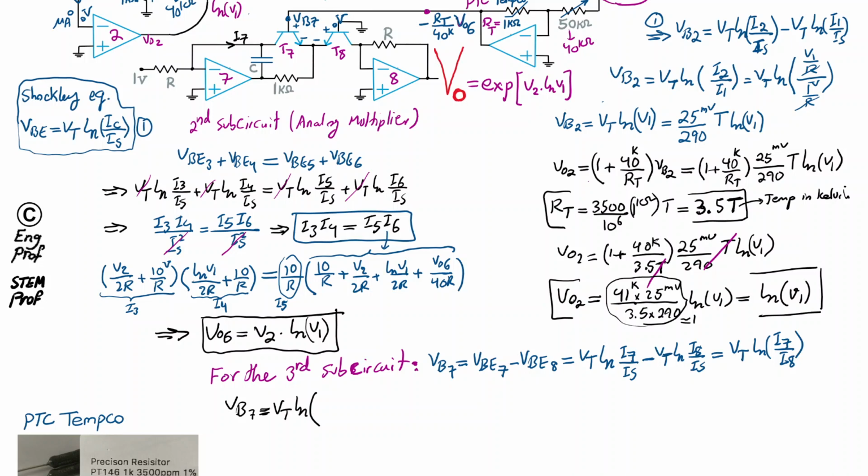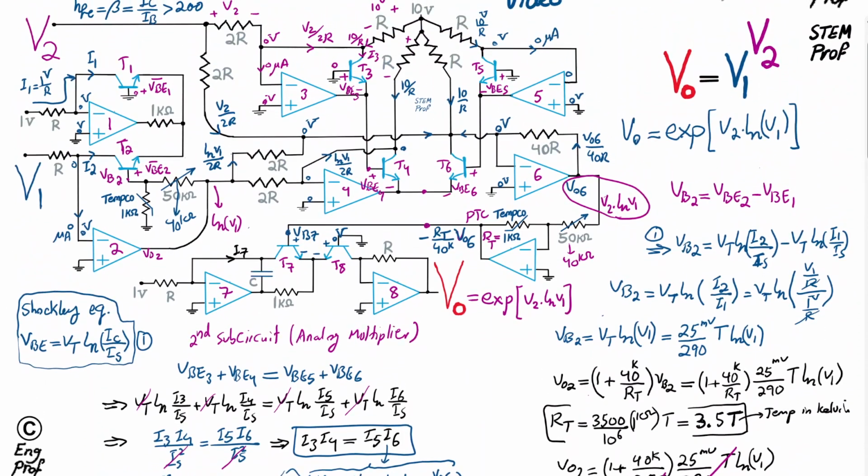And just one note, the cap here is just 10 picofarad, or let's say 10 to 50 picofarad, depending on the type of op-amp and the speed of operation that you would like. Basically, it's a good idea to have this cap repeated everywhere that we have sort of a diode formation, or basically an NPN transistor like this in the feedback loop of an op-amp. That 10 picofarad cap just increases the stability of the circuit and makes sure it is functional.